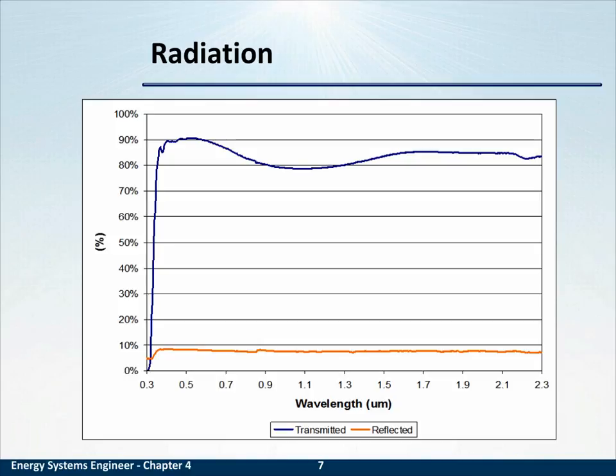So let's say you put in dual pane windows. Well, this graph shows the transmission through single pane clear glass. So you can see the reduction from the glass is somewhere around 10%. So if you put in another pane of glass, you might get down to 80% heat transfer by radiation. So this graph shows that the solution to radiative heat gain cannot be just more glass.